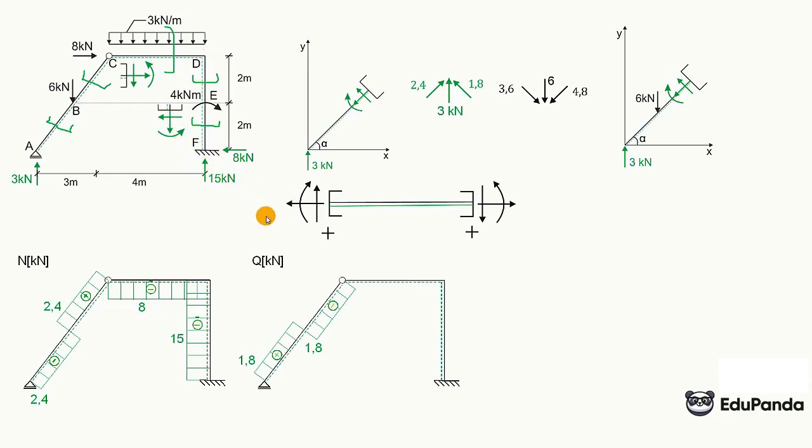And here, yes, we're also looking from the right side. If we stood at this vertex, made a cross-section and looked not infinitely close, but from the right side, the only vertical force would be 15. Then, as we move away with the section, more and more continuous loading appears. So here there will be a linear descent. Remember from previous videos, I talked about this many times. So we have a jump of 15 at this point.